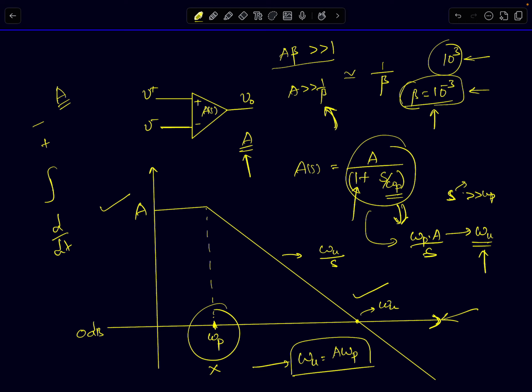There you will worry only about the DC gain of the op-amp. UGB may not really matter for all practical purposes. But if you are going to use this op-amp as a buffer for some high frequency amplifier, or in some filter with some finite bandwidth, then UGB will matter.